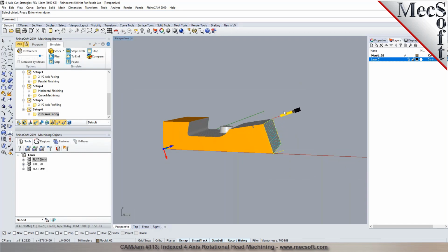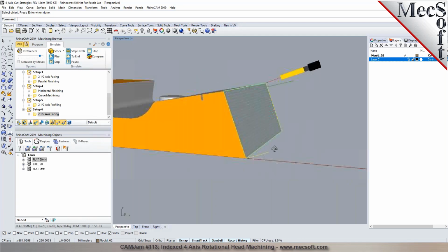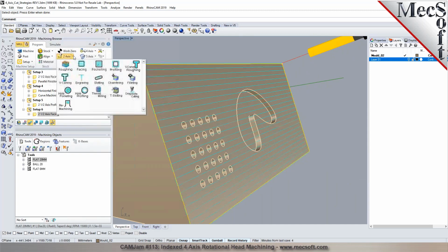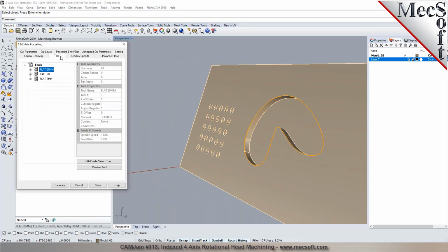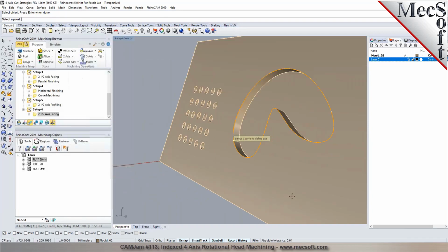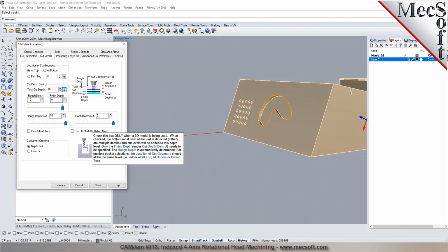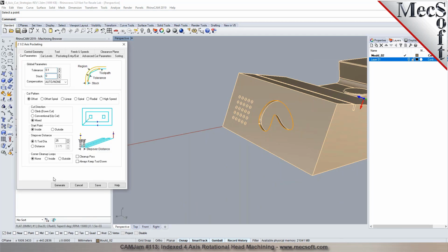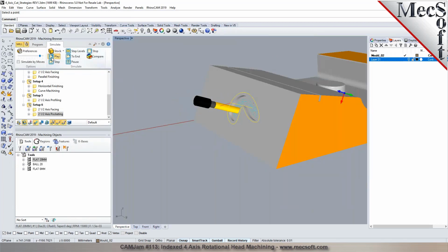If you wanted to do a roughing operation, you could do it. So to do like a re-roughing to remove the excess symmetry on this orientation. Yep. And once you're through with the facing, you want to do this pocket in here, 2-axis pocketing. You can pick this edge. And then I could still use the same cutter. And then all I have to do is pick the depth in here. Okay. I can also say determine using 3D models, so it'll figure out how deep the pocket is. If you want to do rough and finishing all in one operation, you can set the stock to 0. So that gives you the pocket operation.